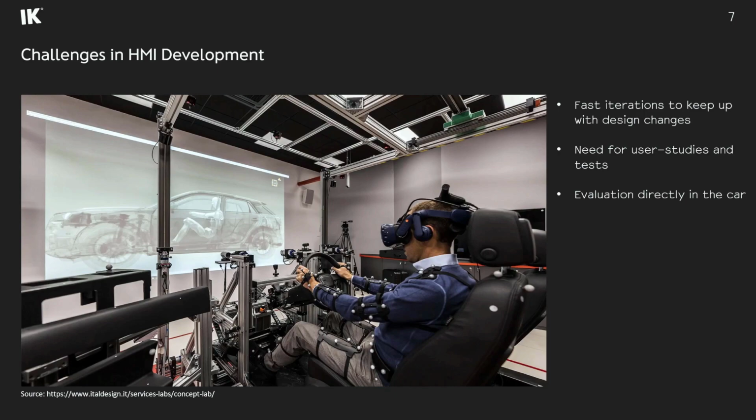There are different setups where you can test your HMI design. So you have a controlled lab situation where you put some test subjects, for example, in front of a monitor or tablet, and see how they interact with the navigation structure of the HMI. But you also want them to sit in a real car, in virtual reality in a car, and then perform these steps as well. And you also want to see if all HMI elements are visible to the driver in any driving position you have.